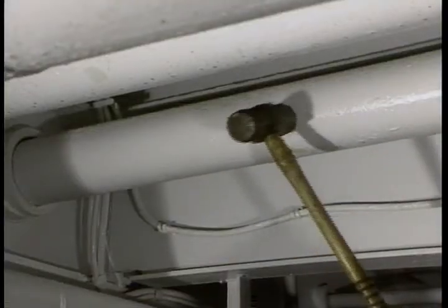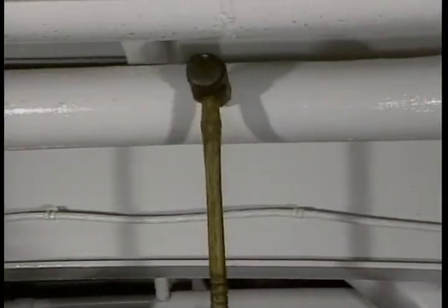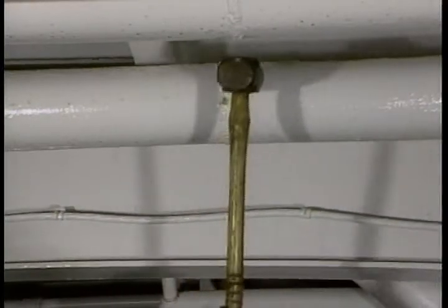About the only way to get a plugged line unplugged is to find the location of the plug by rapping the lines until you hear a dull thud. Then put purge pressure behind the clog and open a vent valve. If you rap it hard enough to set up vibrations inside the pipe at that point, the purge air behind the clog will carry the material off as it dislodges. We don't make it a practice of hammering on pipes, but it is a good method of locating the blockage, and by tapping the pipe you may get lucky and go ahead and break it loose.